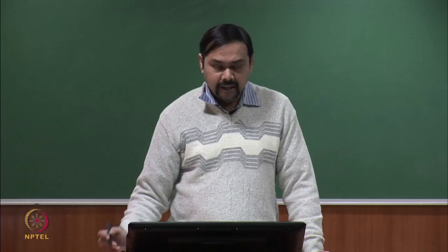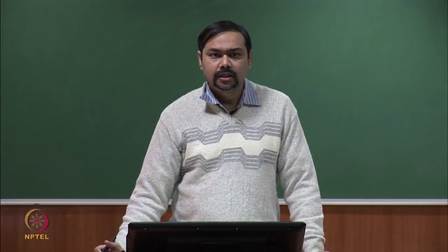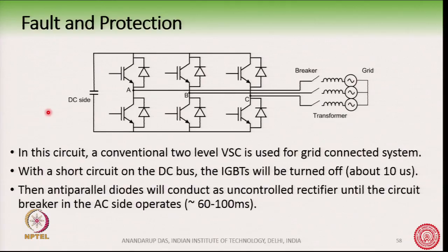There can be many reasons for that short circuit. Another fault that is also very severe is where both switches have been turned on in this leg. It will short circuit the DC bus, so that there is a path here. So one fault that I talked about was the short circuit on the DC bus. You can have a fault like this here.